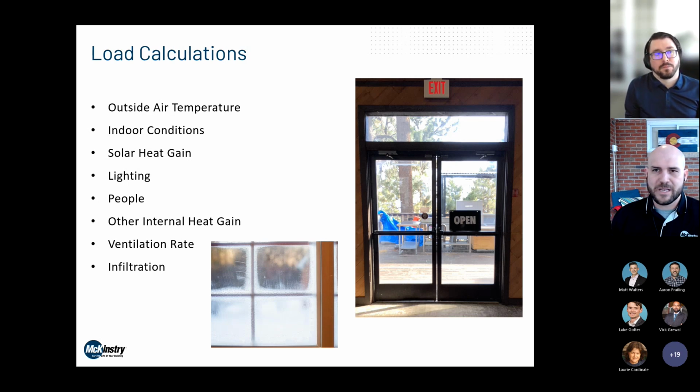You take best guesses as to how well the building is constructed. This is often measured in some seemingly funny units called air changes per hour. A really, really tight building might be like 0.1 air changes an hour. It's never zero. And a really, really leaky building can be more than 1 air change an hour, where the entire volume of air in the space is passing through. At least you're getting entirely fresh air once an hour without anybody trying to do anything. That's far from ideal, but definitely happens.